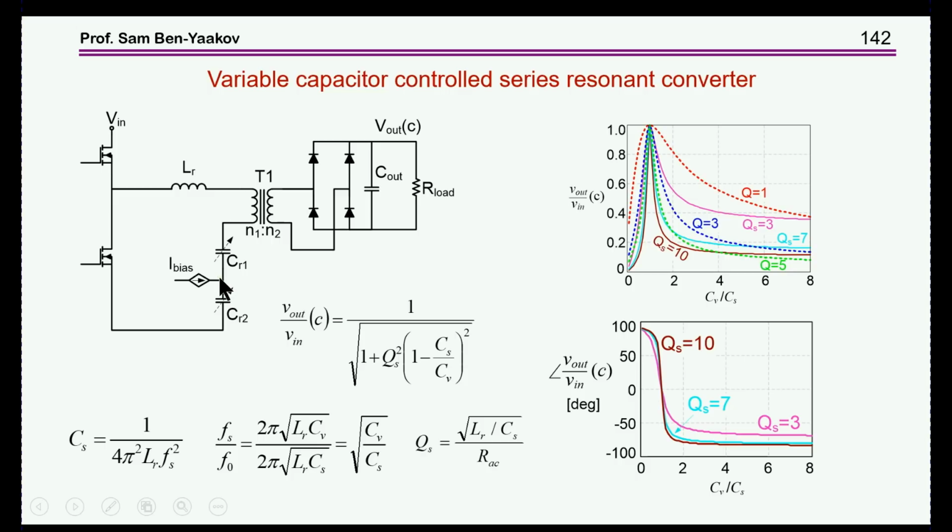And then you can rest till the next time you may need to change the capacitance. How you do it? There are two ways. One is to use a large resistor plus a voltage source, or a dedicated driver that I'll show you that has a high output impedance so that you do not load or short AC the capacitor. This has to be a high impedance here, not to short the capacitor for AC.